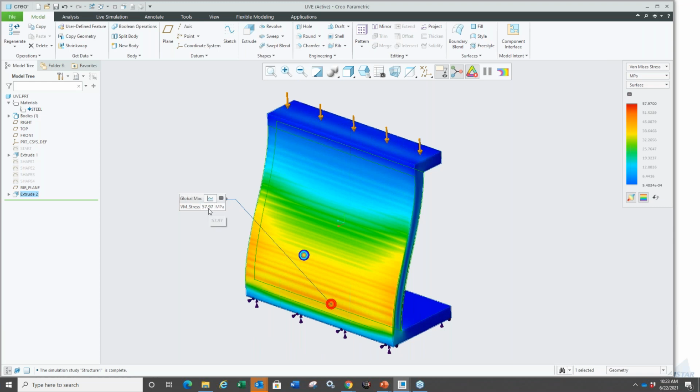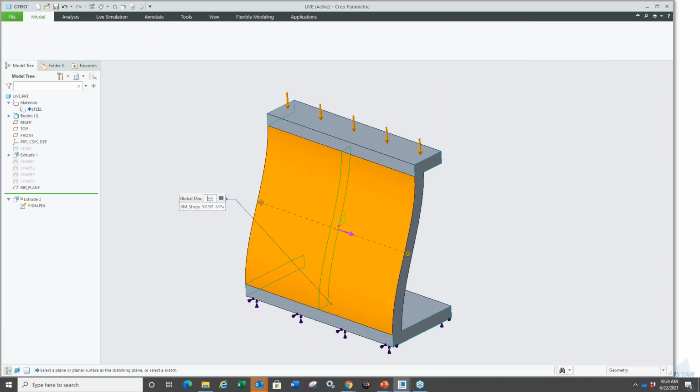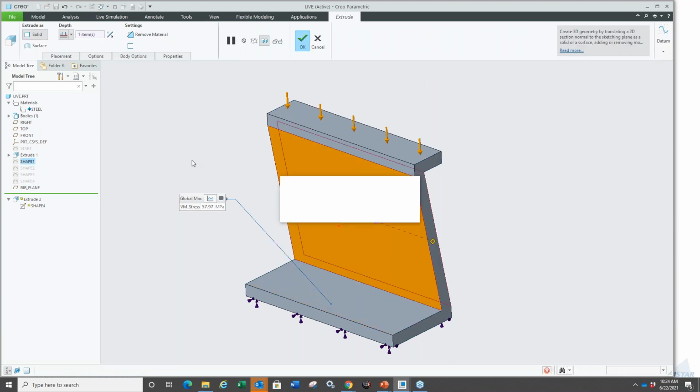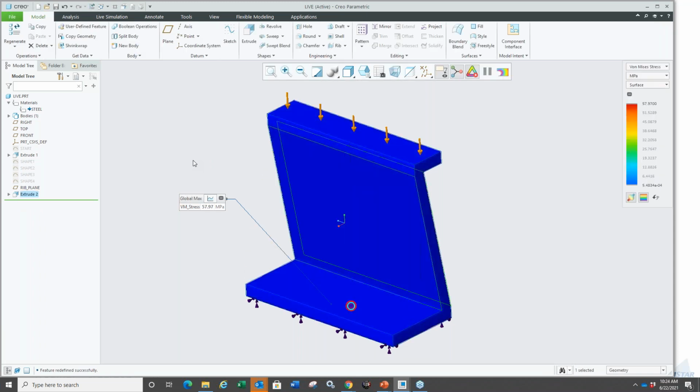So now it's jumped up again, right? So I'm thinking, you know, maybe the first one that I used probably was 15. Maybe that is the lowest one. Maybe I should just go back to that, right? And then see further if we could improve it, right? So I might compare this with my yield strength of the material, right? I might want to have a good factor of safety. So all that you would typically do in FEA, that applies here too, right?